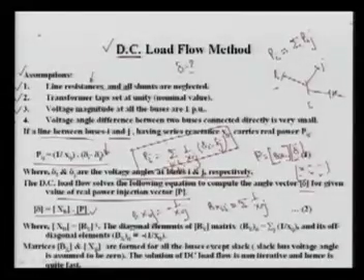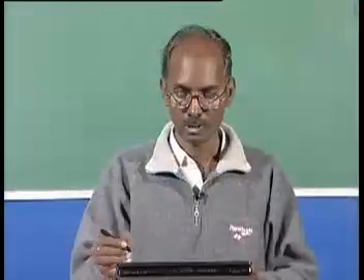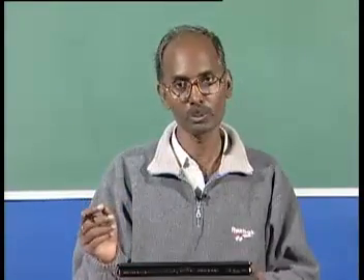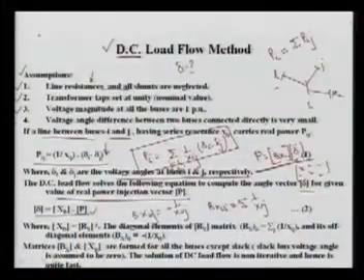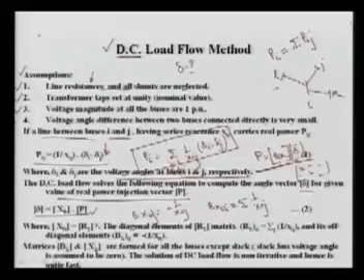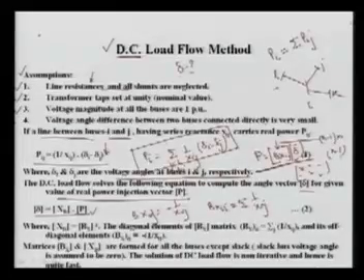So we can have this matrix. Now we can exclude the slack bus, so delta at that bus is assumed to be 0. P also we can ignore because the losses etc. are met by the slack bus. So this matrix is nothing but n minus 1 cross n minus 1, and that is a square matrix. It is a non-singular matrix as well, so we can invert this.